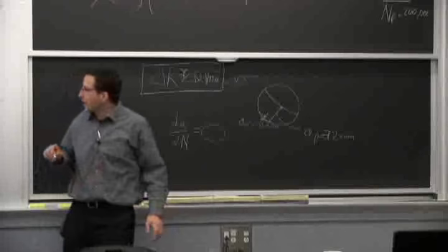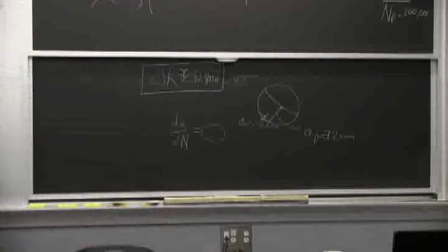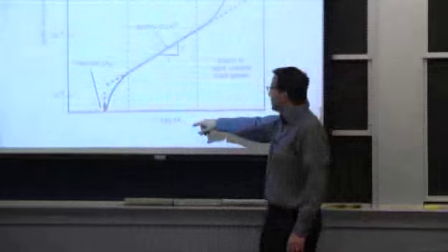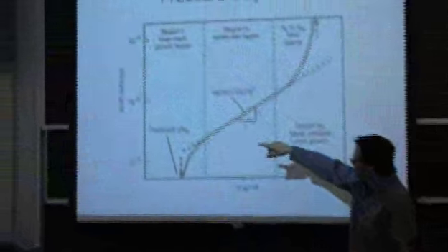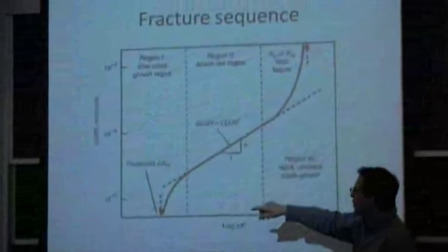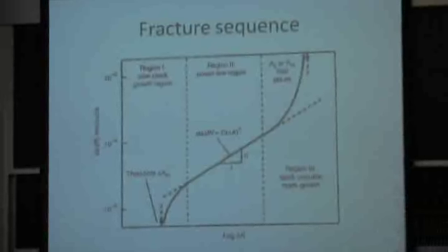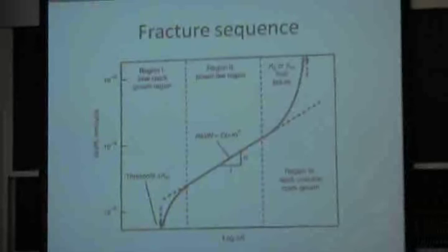And the equation I have on the board tells us that, and there's a logarithmic function here for that demand of stress intensity. It gives us the shape of how the crack growth rate, that's the dA/dN, same thing we talked about here.